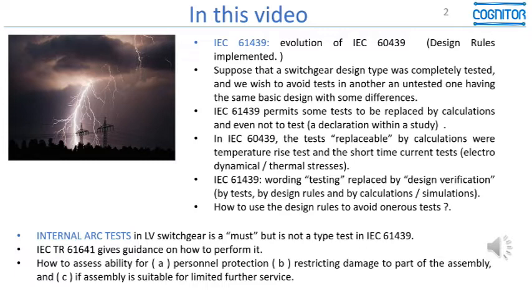This can be done by tests, as before, by design rules, and this is new, and by calculations or simulations, in some cases where design rules do not apply completely. We'll show here also how to use design rules to avoid onerous tests, related to internal arc tests in low voltage switchgear. Internal arc tests are not type tests, but they are becoming a must in the market because most of the panel users are requesting it.